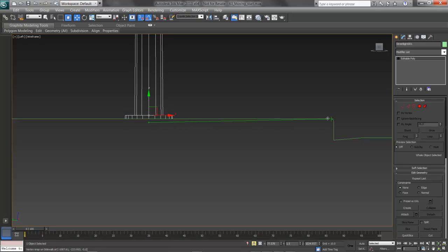sidewalk. What we see here is the benefit of using the axis constraints, and there's my yellow rubber band showing me clearly. I started my snap at the bottom of the street light, over here to the left of the curb. I'm grabbing on the bottom, pulling up on the Y-axis, but moving my mouse over to register on another point, and there's that yellow plus for the snap. It's great because it lets you register to things that are not directly above the object, so you can snap things perfectly into place. And the more things are snapped, the better off we'll be, as that means our objects are light tight and won't see artifacts or odd shading when we put our lights in.